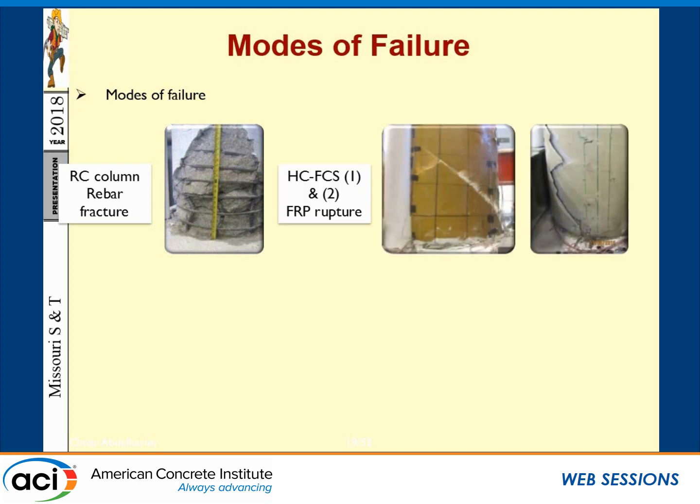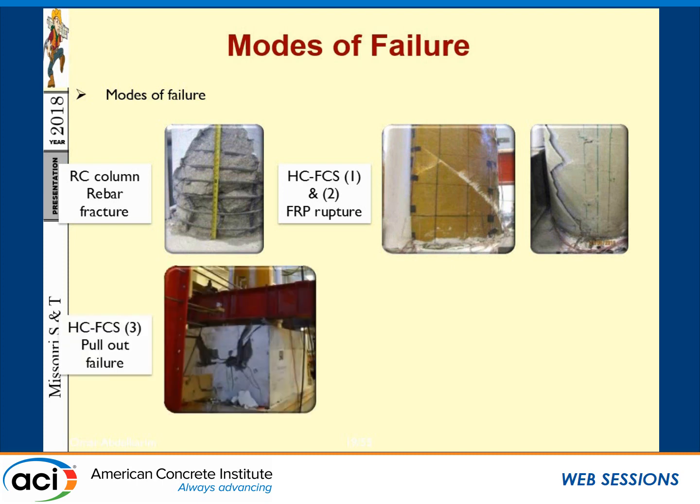These are the two FRP, the hollow core columns. The first one, this is the one with the thick glass fiber. So this is a 3/8, and this is the thin glass fiber. So both of them fail more or less at the plus or minus 53 angle. This is the angle of the fiber. So when we did these, the glass fibers are filament wound at plus or minus 53. That means you have, and this is your fiber. You can see over here. This is the angle of the fiber, 53, and this is where you obtain your failure at this angle.